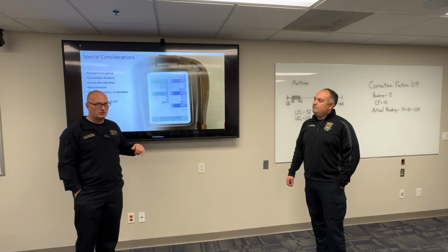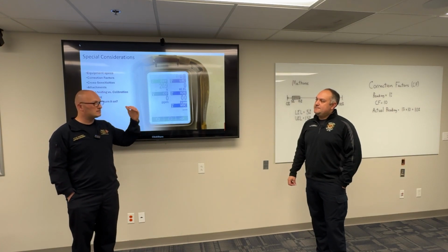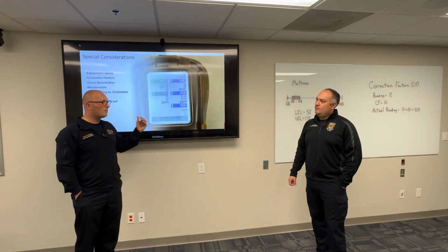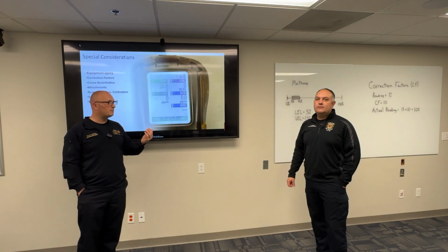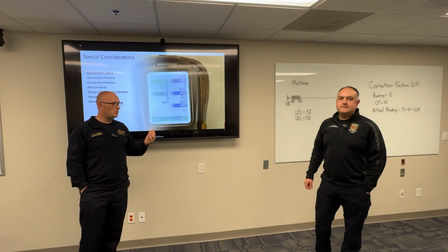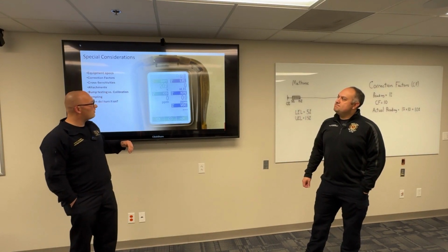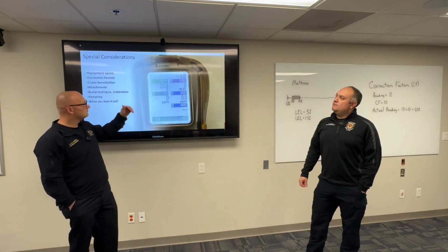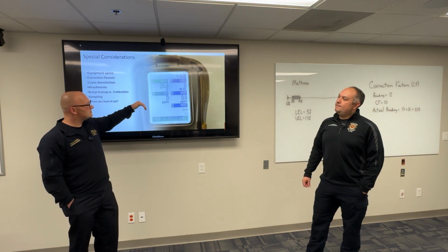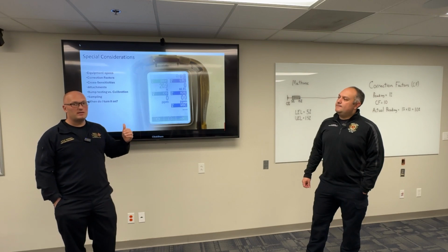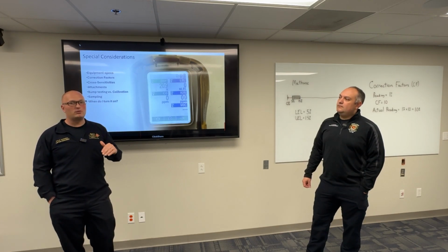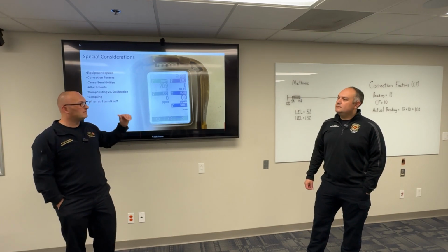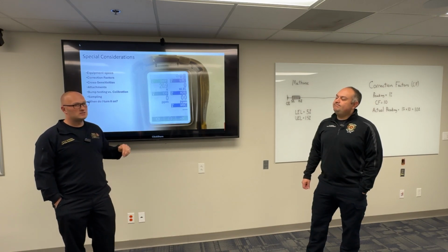Watch what my VOCs are doing. If I get into somewhere and I start getting something on VOC, it could be a low number, but that's still the meter showing there's something else in the air that doesn't belong. So just because I run a call, hey, I've got an odor of natural gas, or I've got a CO reading, I need to be methodical, do my due diligence, check everything, and pay attention to the small things on these meters.